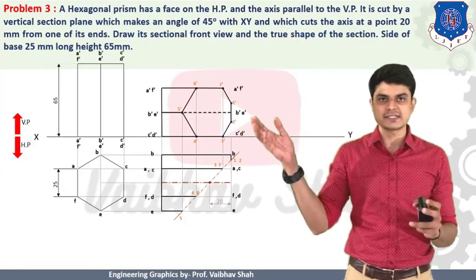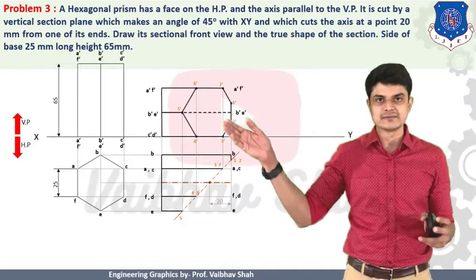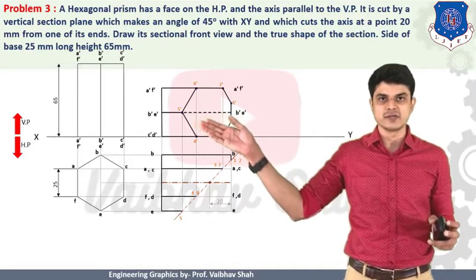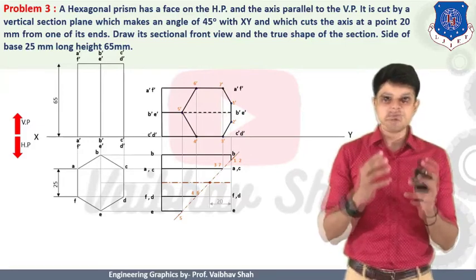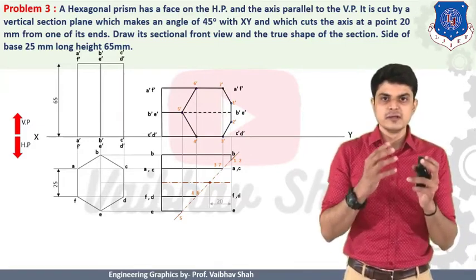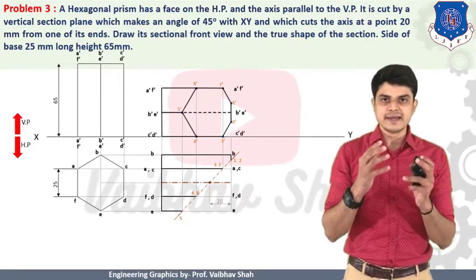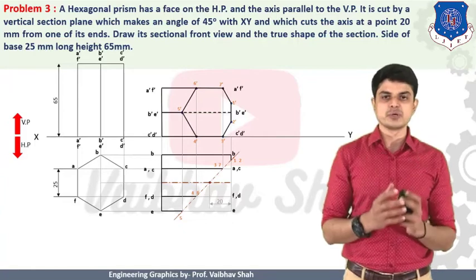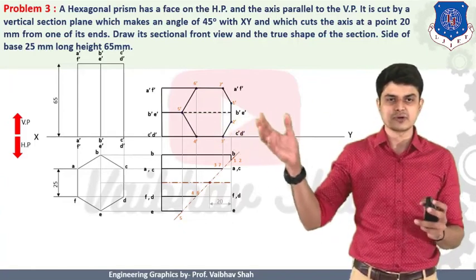But here in the cut section, we are not having any E lines. We can specify this dotted line, but here we are having point E and solid lines. We should plot a solid line. So always remember when you try to join the points, and if you are having the dotted line and solid line at the same time, you should give preference to a solid line. So in this case, we have drawn this solid line darker, and this is your dotted line.